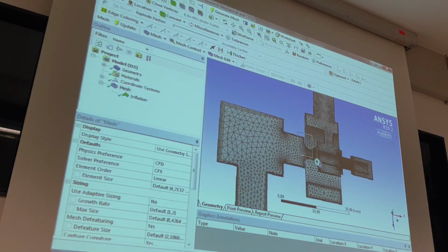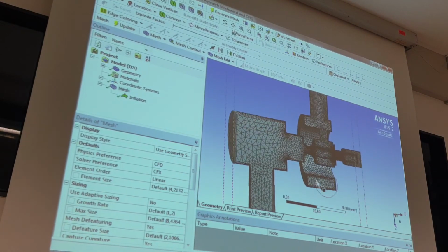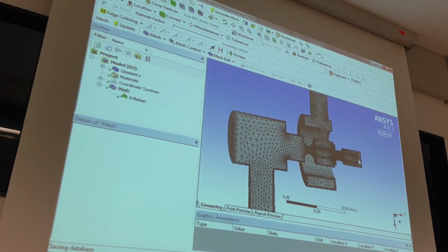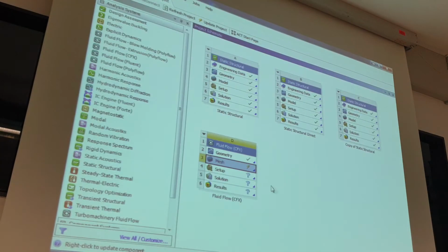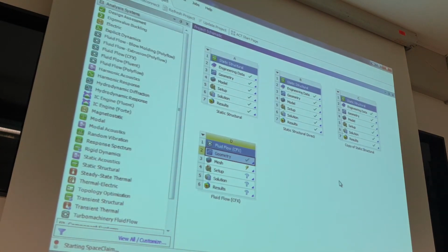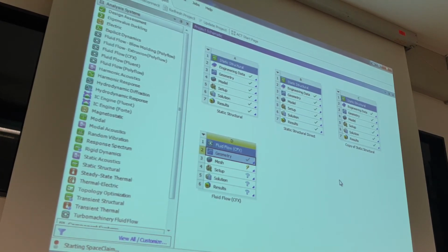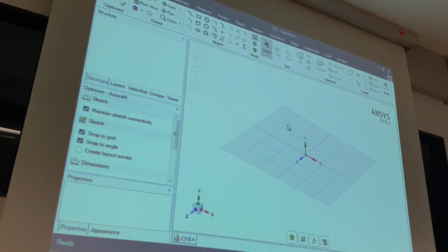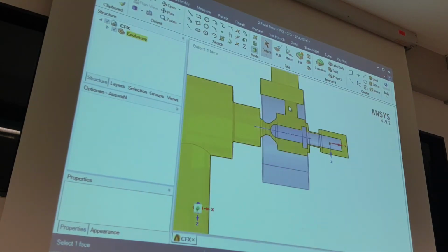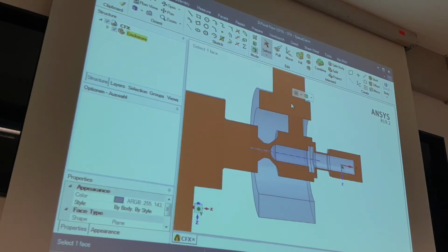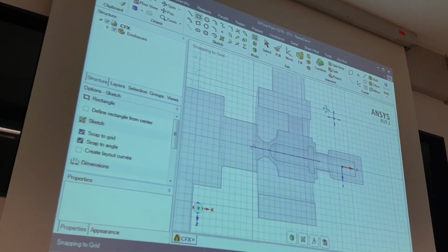Did you understand? Now it's good meshing. For example, in your examination there will be the question, how can we create hexamesh? So, if I see this, first of all, it's not this tetramesh. You see, tetramesh is really bad. If you make something finer, then everything is finer, so it's really not optimal. It's much better to create hexamesh from the beginning. How can I create hexamesh? Very easy. I see I have maybe three places.